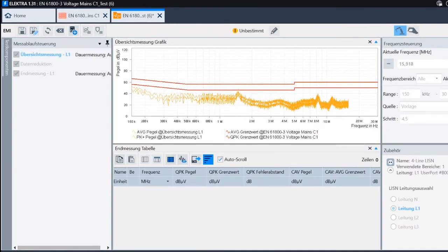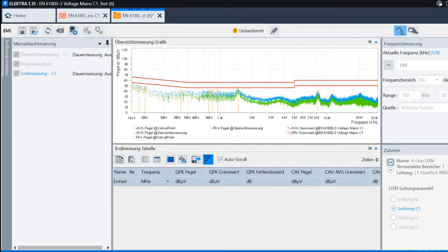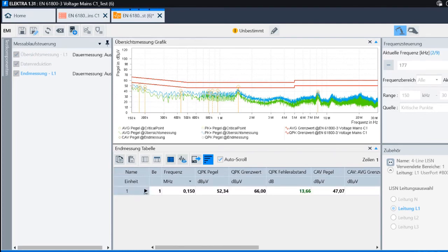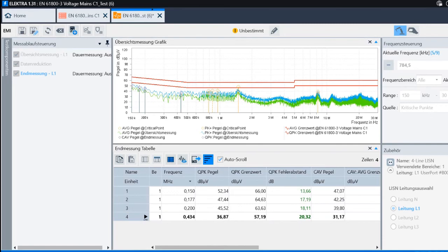So now we can see one of the next measurements where we attached the 25-meter cable length to our drive, and we changed back to the high performance version, so the one with the higher leakage current. But we are still below the limits for 25 meters and class C1, which is pretty good for such kind of standard filter and the surroundings we are in at the moment.